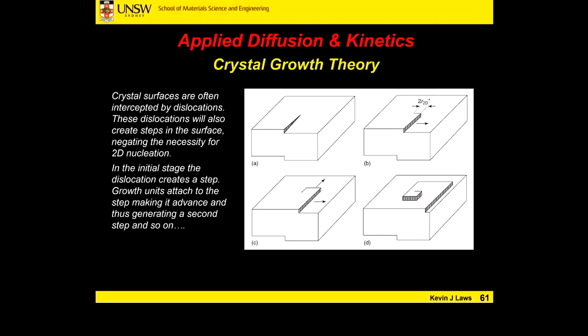The most common type of flaw in our crystal structure is a dislocation, and we can have different types of dislocations, edge and screw dislocations. They have a different structure and makeup and orientations. But essentially what they do is provide a pre-step or flaw in our material. By having this pre-step or flaw, it's already providing us with essentially a growth site or a step.